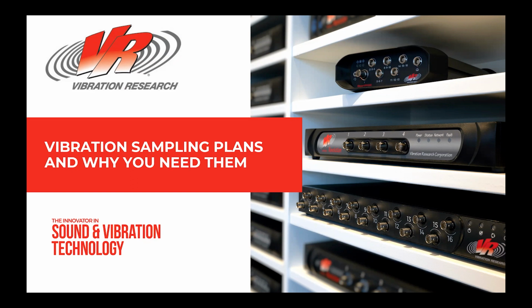Today, we are going to take it one step further by talking about vibration sampling plans and why you need them to ensure robustness in your product. We will explain what a vibration sampling plan is, the math behind the Weibull success run formula, and how to apply it to your particular vibration test. Doing this will not only make your vibration tests more meaningful, but will also provide realistic insight as to whether your product is ready for release to commerce.